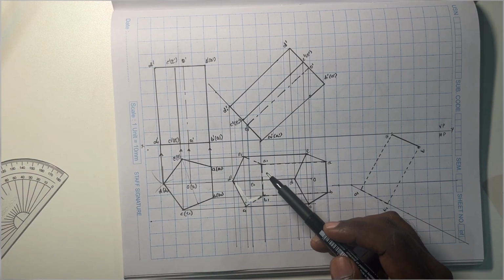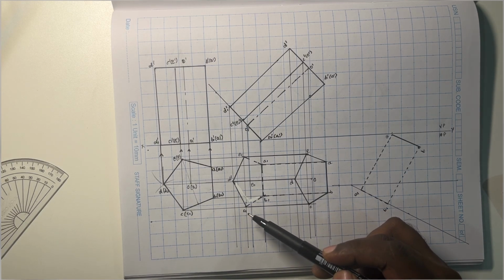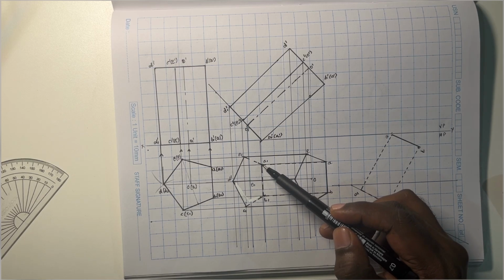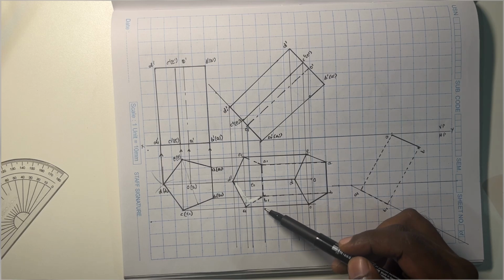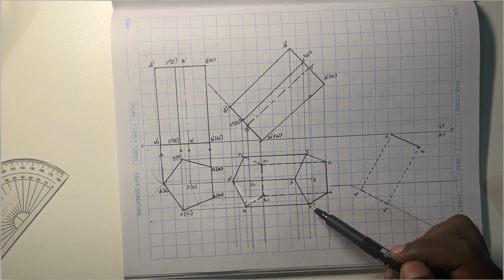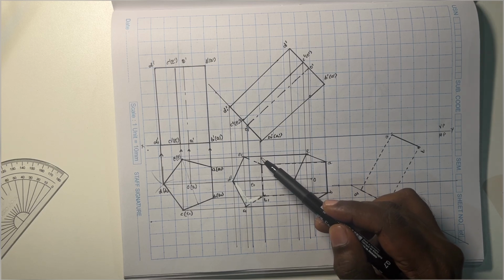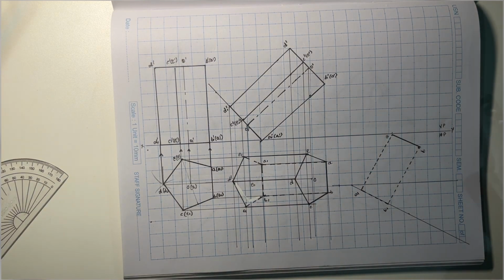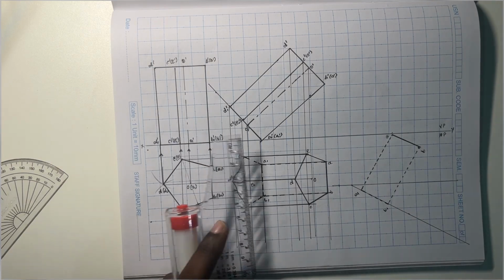If I have to locate the points E1 and C1, I can just see that E1 and C1 are on the same straight line. So what I'll do is I'll just consider the distance from A1 to this projection line, that is on E1 to E, and B1 to this projection line, that is C1 to C. I'm going to measure this distance and make an offset of this dotted line, that is A1A, to this distance, and from here I'm going to measure E1 to E. So that is how I can locate the points E1 and C1. So I can just measure here.